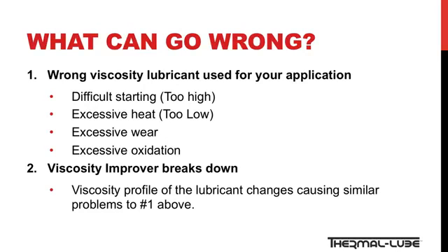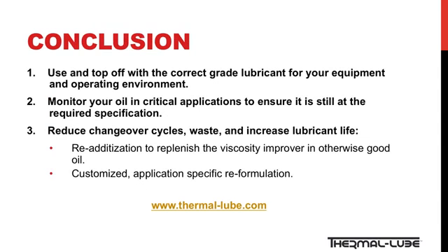First, if the wrong grade lubricant is used, or a wrong grade lubricant is used to top off a reservoir, the change in viscosity can lead to difficulty starting if it's too high, excessive heat if it's too low, and excessive wear and oxidation of the lubricated components. The second issue is that over time the viscosity improver added to base lubricants breaks down. This is a function of the operating environment and overall endurance of the viscosity improver additive. At a certain point, the viscosity of the lubricant will change, and you will encounter the same problems as having the wrong lubricant grade. To conclude,